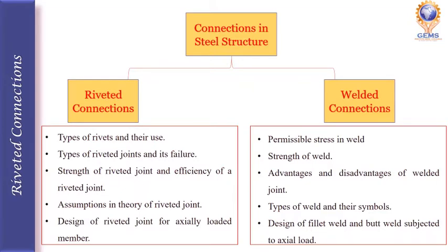Under the welded connections, we are going to see about permissible stress in weld, strength of weld, advantages and disadvantages of welded joint, what are the types of weld and their symbols, and design of fillet weld and butt weld subjected to axial load.